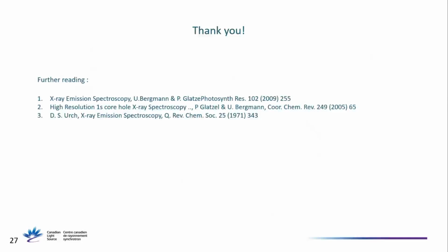Yes, maybe a suggestion. You were saying that you were having problems with some of the 3D printed material because of warpage. It could be useful to switch to a different plastic to prevent warpage. Now we have a better 3D printer, which probably gives better printing. We have tested. You can also anneal plastic. I didn't realize it's semi-crystalline, and annealing can get rid of the strain in it that can prevent warpage. With the new printer, we're using a different material, which is much better.